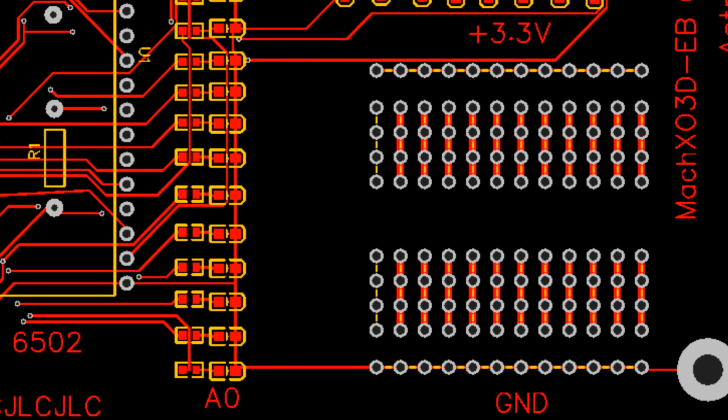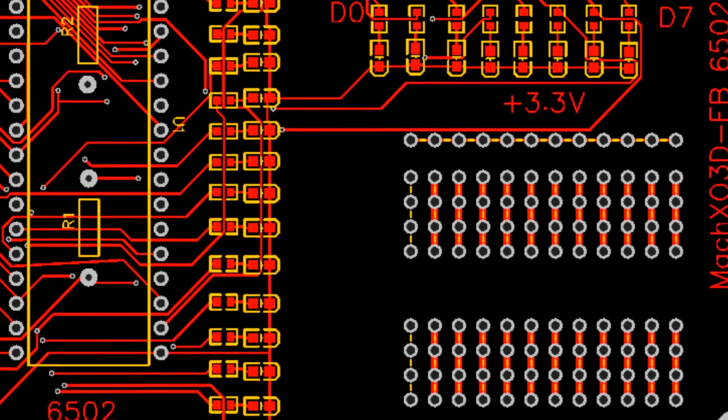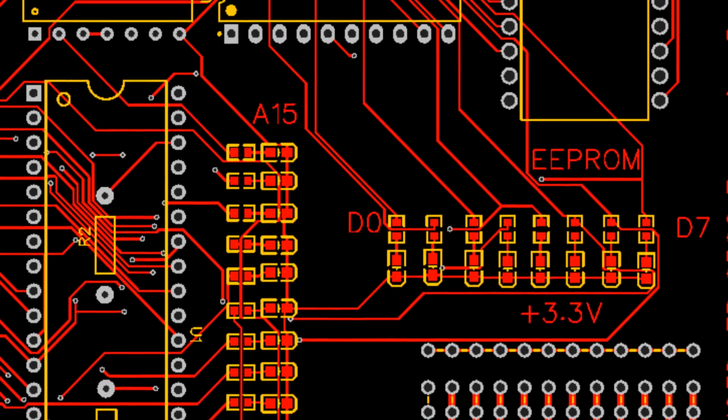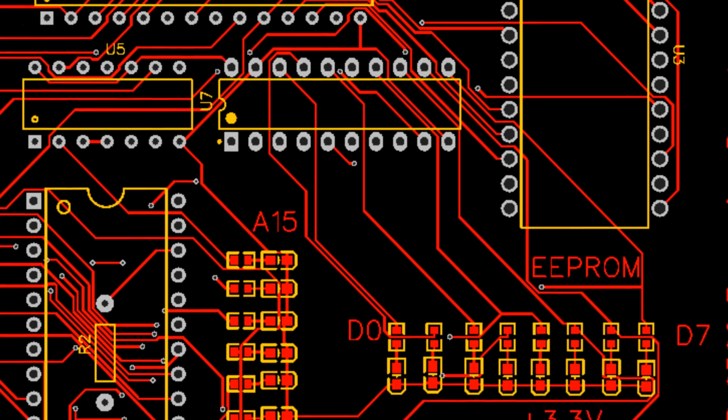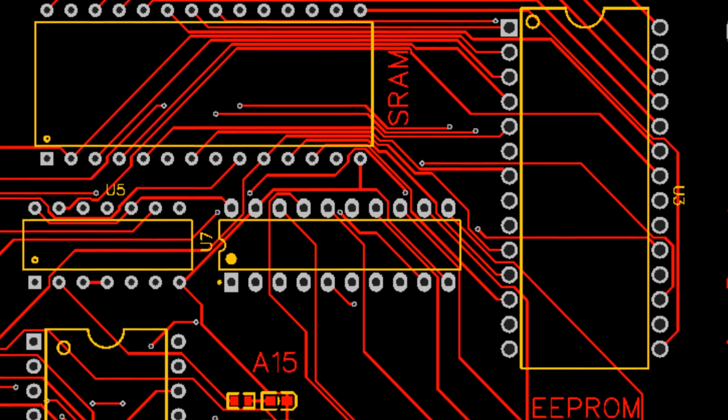This turned out to not be the case, and the bus transceiver needs to be turned off whenever the FPGA is selected by address lines. Because of this, I had to cut some traces and connect botch wires to some pins.